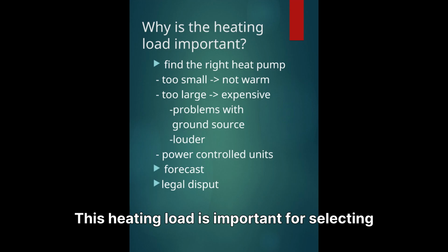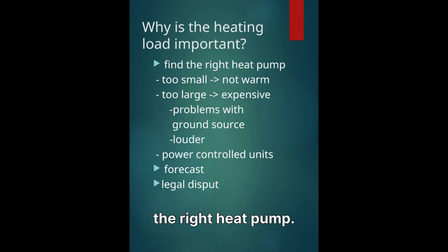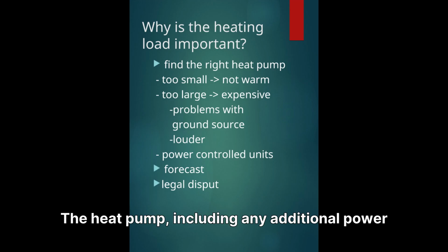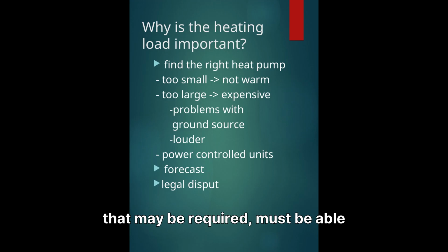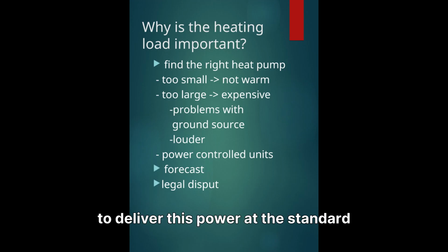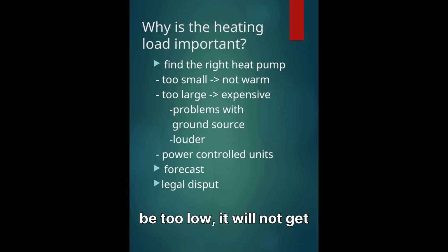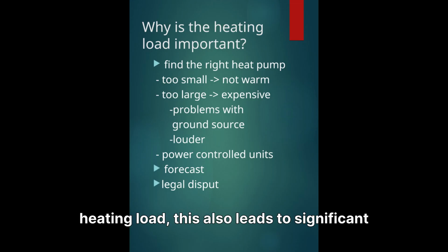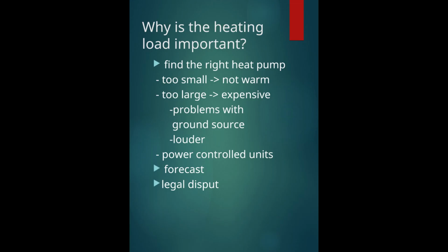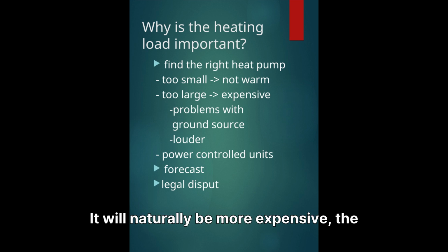This heating load is important for selecting the right heat pump. The heat pump, including any additional power that may be required, must be able to deliver this power at the standard outside temperature. If the heating load is assumed to be too low, it will not get warm. However, if you err on the side of caution and assume too high a heating load, this also leads to significant disadvantages. It will naturally be more expensive.